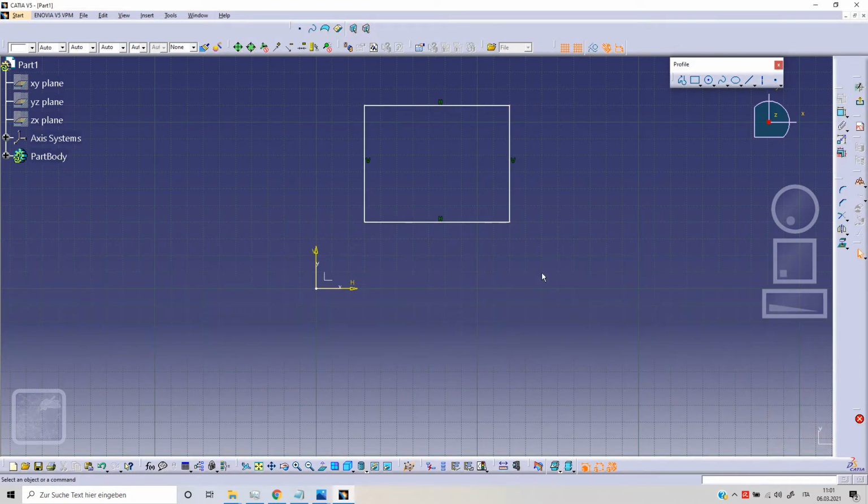And to fix the position of our rectangle in our space, to obtain an isoconstraint sketch, we need to specify the position. As you can see here, we need to specify the position of 4 different points, or we can fix this height and we can fix this base, and for example we can fix the position of our point.